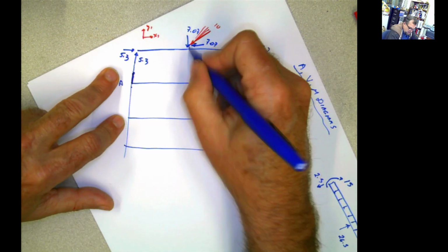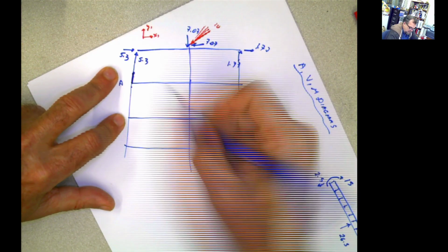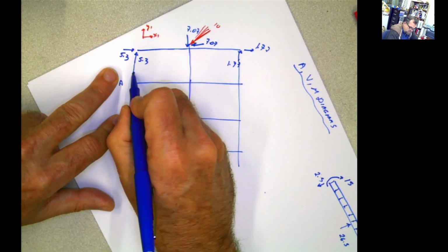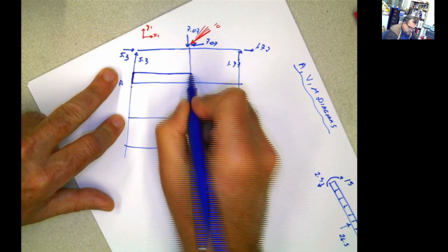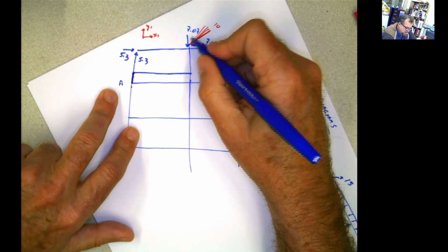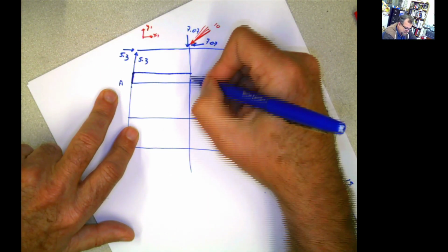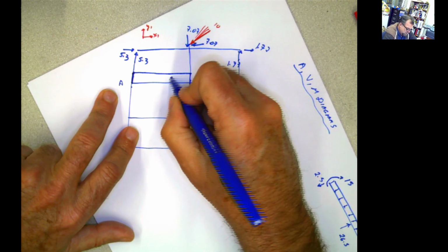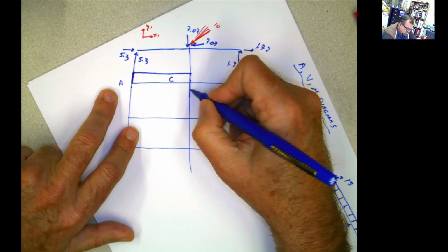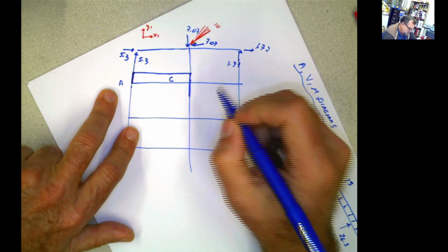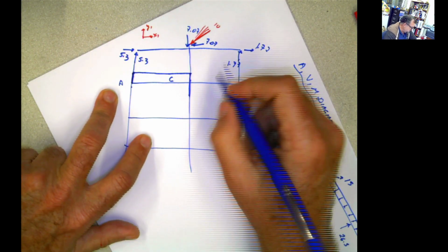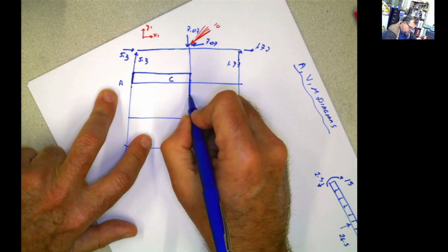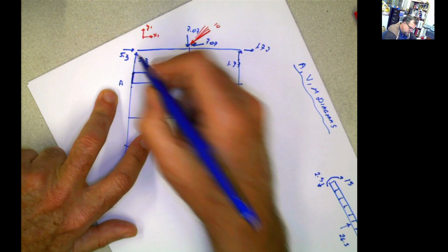And then, of course, you need a line here. It doesn't have any other axial force up to that point, so we go constant. Here we have a 7.07 pushing it down. There's going to be compression, pushing it down, and this is pushing it down. It's going to be up to this point here, so this is compression, and this value here is going to be 7.07 minus that